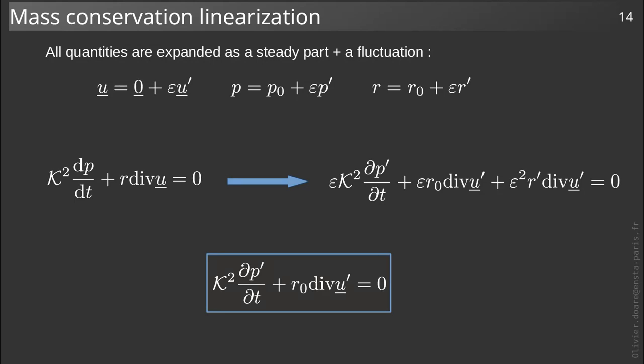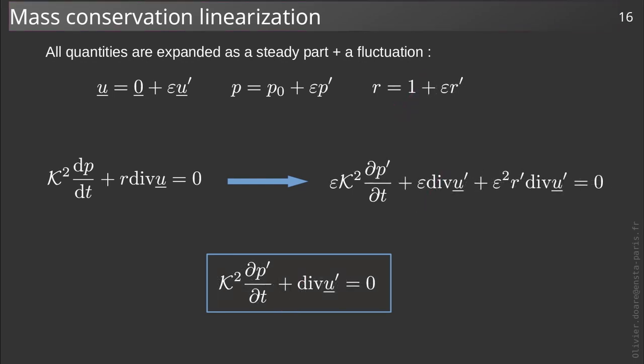However, it is not relevant to continue to take into account this case because it happens mainly when there are temperature gradients or salinity gradients in water. Since we do not take into account thermal effects or possible chemical effects in our analysis, we can therefore set this term to 1, since the reference density rho 0 was used to scale the density.